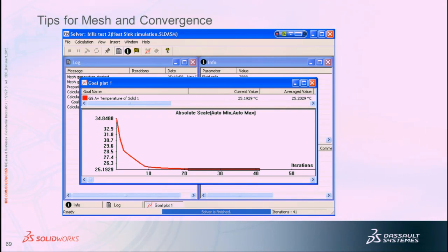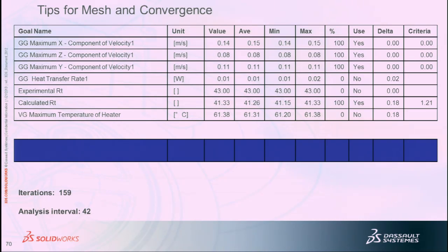That's what it's comparing here, because you don't want to compare the last 2 iterations; you can be on a slope downward or upward. This is how CFD analysts do it in other codes too. They'll look at 50, 100 iterations. In Flow Simulation, you can change the analysis interval if you want, in the Calculation Control Options command. But the default is usually pretty good, and it changes depending on the problem that you have. So it's smart enough to recognize that.